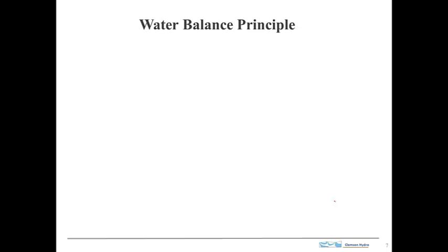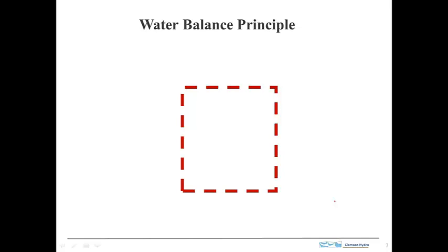Another process that overarches all of hydrogeology, and will come up many times in what we do, is the water balance. This is really a specification of the conservation of mass principle from physics. It allows us to solve a variety of problems in hydrogeology. It also allows us to think about our data in important ways. So it's really fairly straightforward. To apply the water balance, we need to first identify a region over which we'll take the balance.